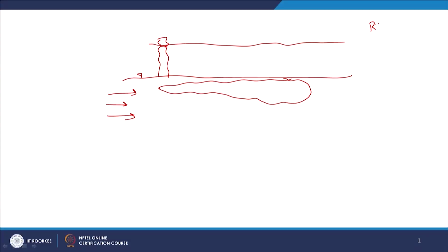And so we started looking at PRBs. What are PRBs? Permeable reactive barriers. Typically, as we mentioned earlier, they are constructed subsurface. This is the side view, and it's permeable. Though we call it a barrier, it's permeable. The plume is going to now flow through this reactive barrier, so you have my reactive media here. I'm going to choose my reactive media based upon the relevant contaminant and this particular plume. We are going to design the PRB in such a way that as the contaminated plume moves through it, you have the relevant removal to meet your regulations or your design.